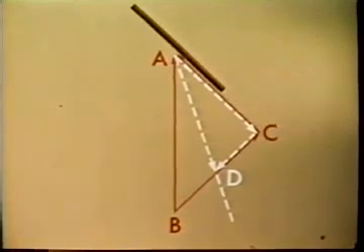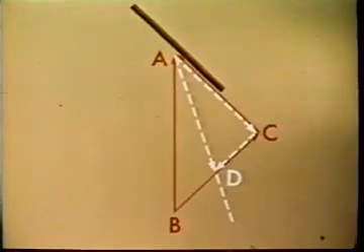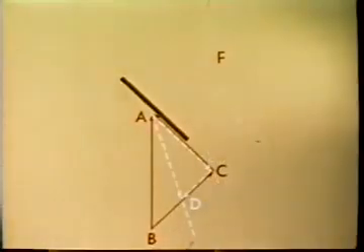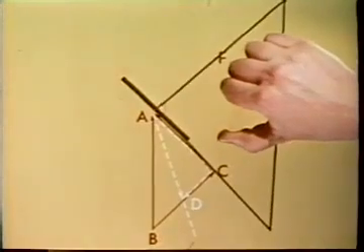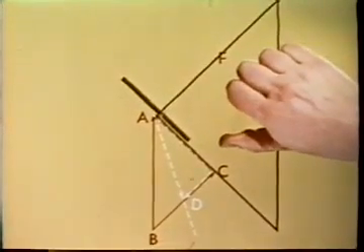To find the largest possible angle of the flight path to the vertical, this geometrical construction can be materialized using a draftsman's square and two drawing pins. The pins are placed at C and a point F situated vertically above C at a distance equal to AB.